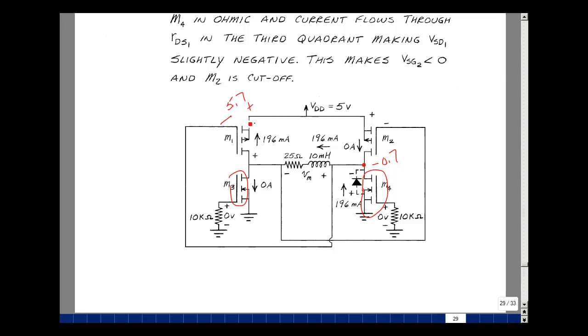We've got a low resistance. The voltage across here is pretty small. We say it's roughly 0. Now let's calculate the voltage here. It's going to be 5 volts, and then this terminal over here is hooked up here, and the voltage across here is approximately 0. This node voltage is going to be equal to 0 plus 5. 5 minus 5 is going to be 0. It's going to also cut off this transistor and have no current flowing.